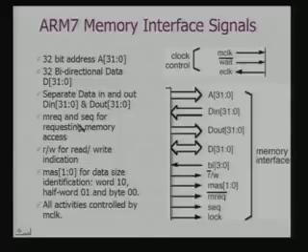M request and ACQ, these are two signals. This is an active low signal, M request. This indicates whether your ARM core is requesting memory access or sequential memory access. At this point we shall see how to use this signal for efficient access when we are interfacing with external memory. Read and write are for read/write indication.